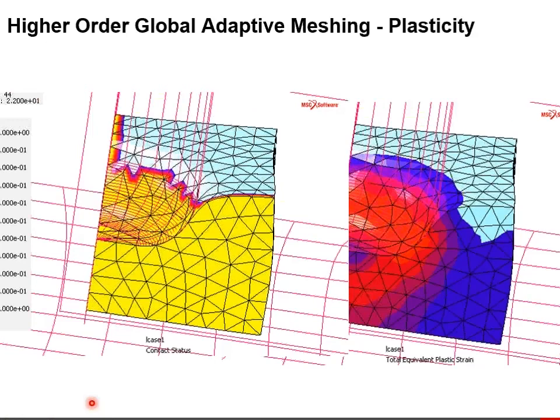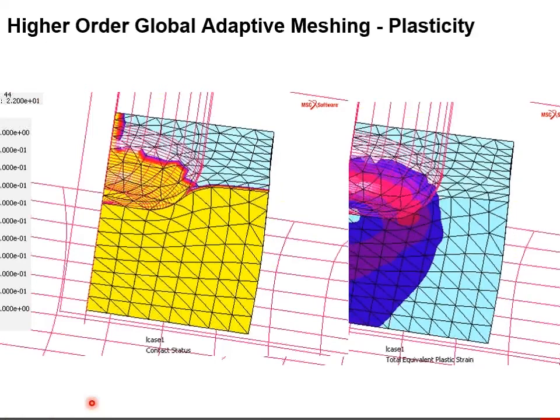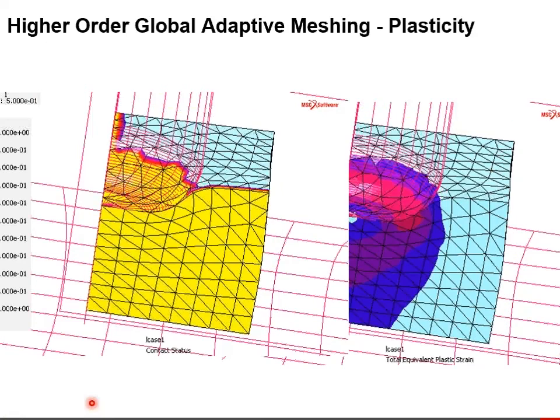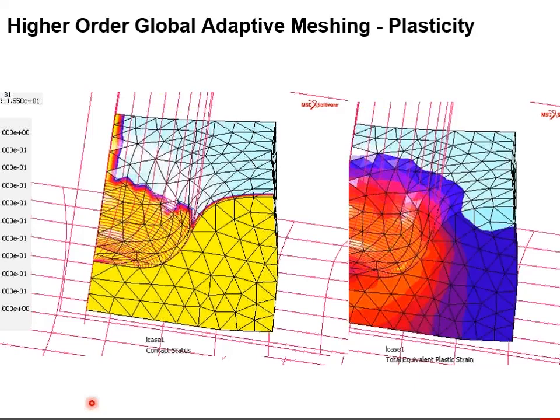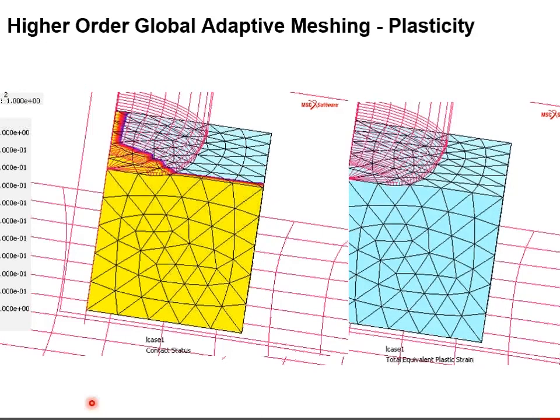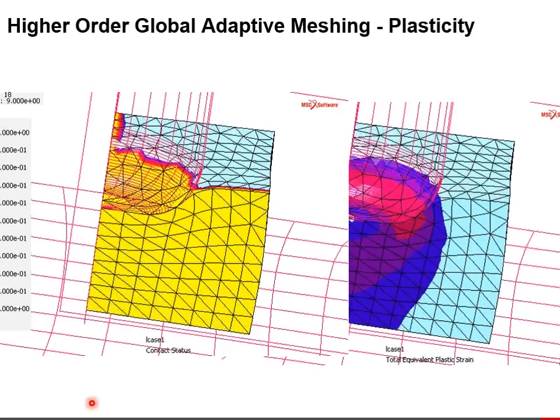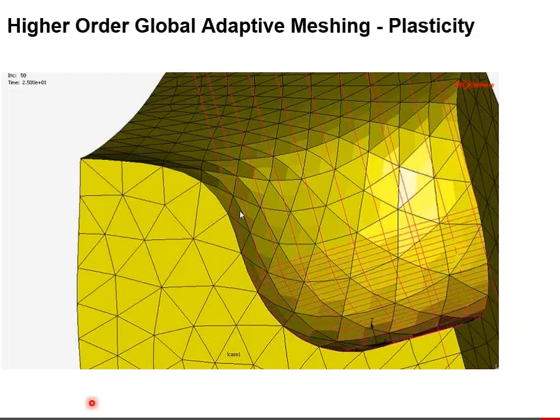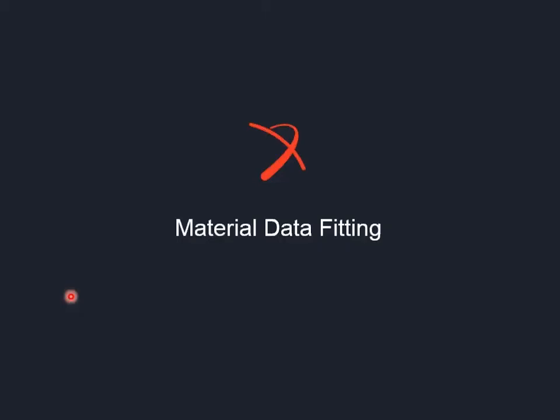One should take some caution, though, that with using higher order elements, if the mid-side nodes are really not in proper locations, you're actually likely to get an inside-out condition because of the Jacobian of the element. So we can see that here in sort of a final plot. You really see that these tetrahedral elements have nice curved surfaces, and it truly satisfies the contact condition very well. The next area that we did a lot of work on, which is really evolutionary.